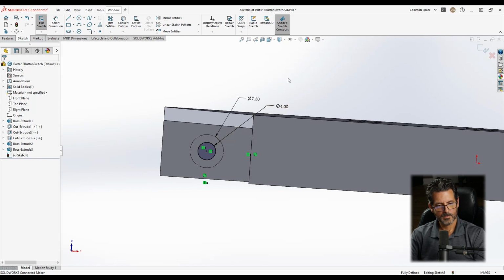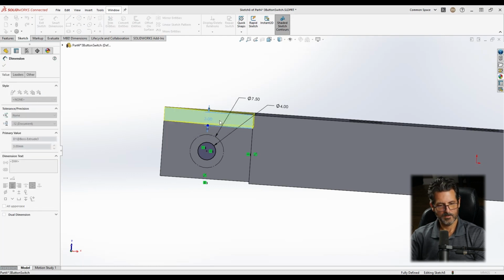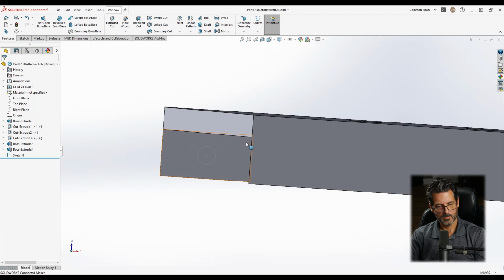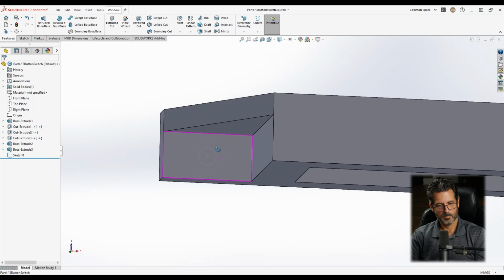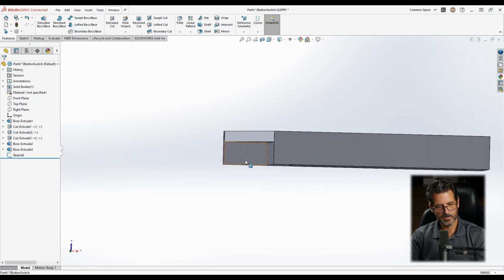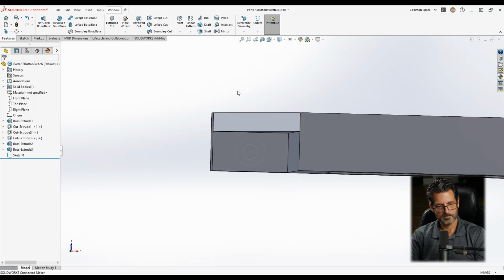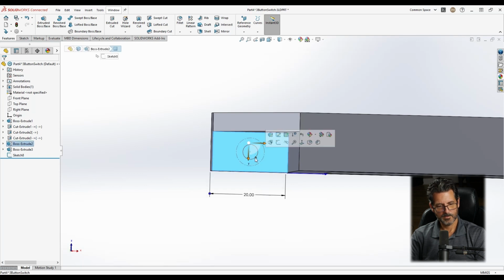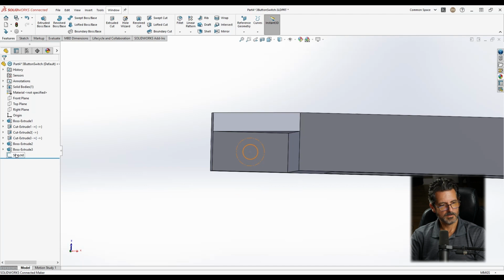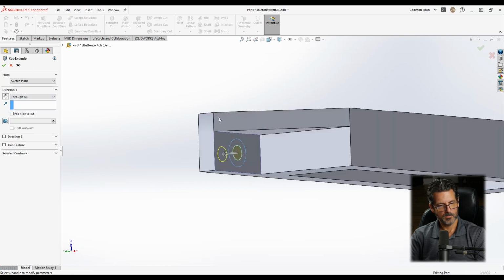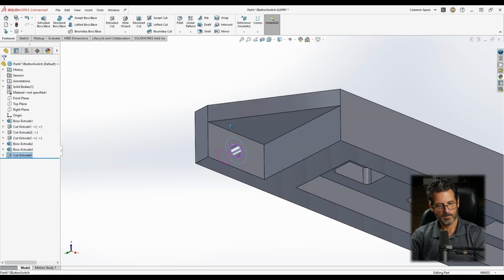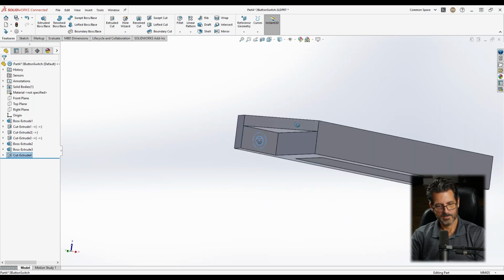And now I'm going to change the thickness of this back to, let's see what 5 looks like. Plenty of room there. Okay, we're going to use that right there as the hole. So let me go ahead and select this sketch and say features, extruded cut, through all. There we go. All right, so that's this side.